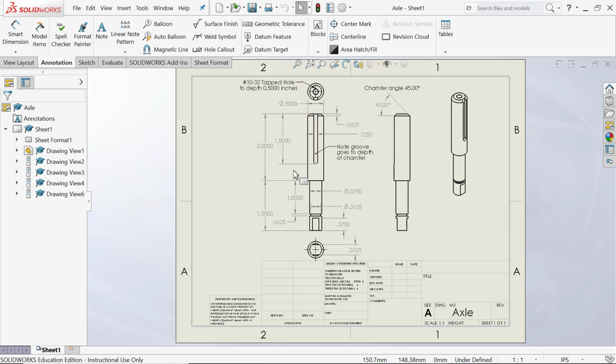Our front plane will be perpendicular to us if we look at it like this, and our right plane will be perpendicular to it if we look at it like this. Does that make sense? By having our origin in the very center of this, then when we go to put this screw hole in here, we know the center of the screw hole just has to be on the origin as viewed from the top surface.